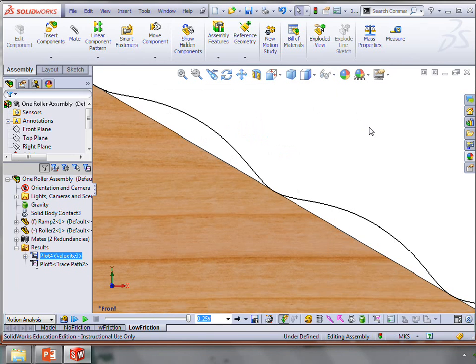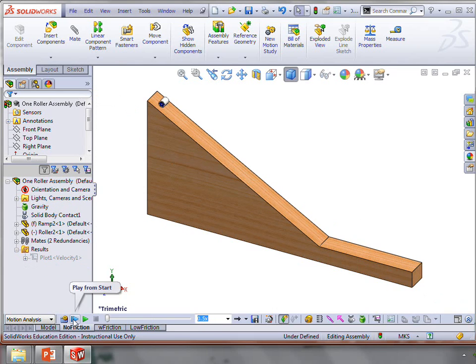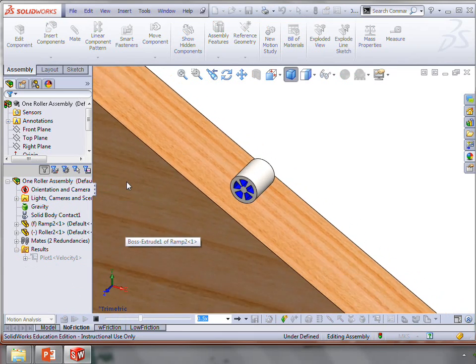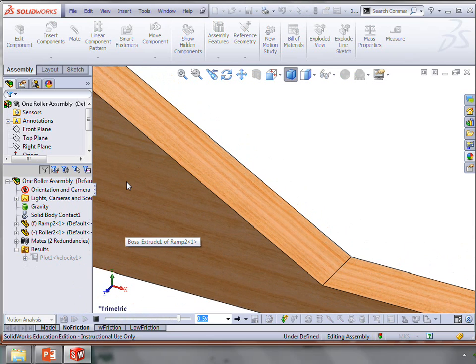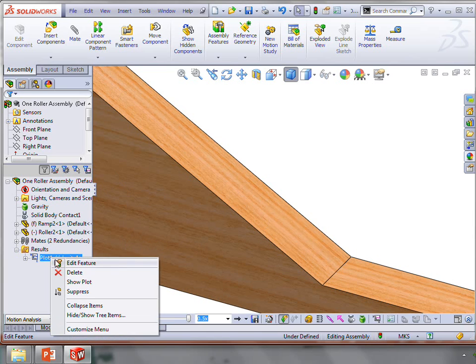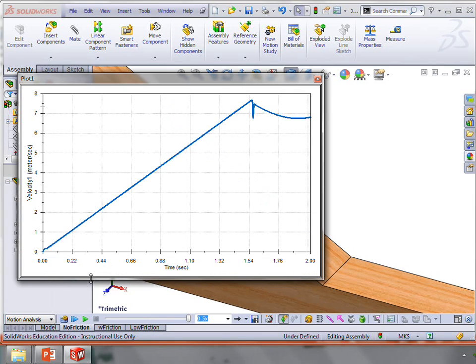And again, the other extreme case is if we look at it with no friction at all. In this case, you can tell that we're pure sliding and not rolling at all. So we would get the same solution here. Really, we're treating this as a particle when we do that. And so there's our maximum value of speed that we can have, it looks like it's about 7.5, 7.6 meters per second.